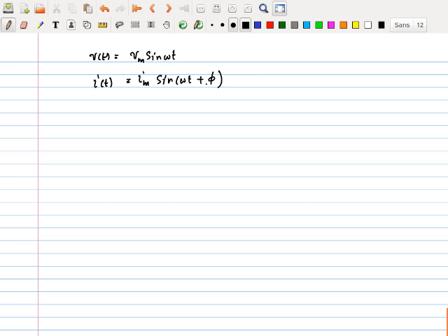If it was a capacitor, that will be minus 90. That's what you get for phi. But let's say it is this: some element, I don't know what that element is, the V and I are phase shifted as it goes through. Now tell me, what is the instantaneous power? It is again v(t) times i(t), and it can be written as VmIm times sin omega t times sin omega t plus phi.